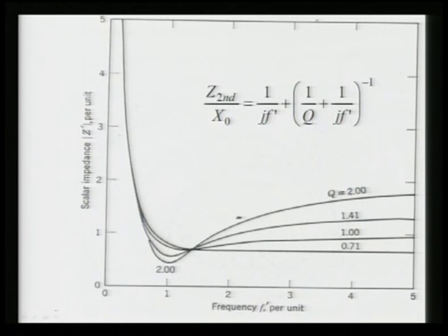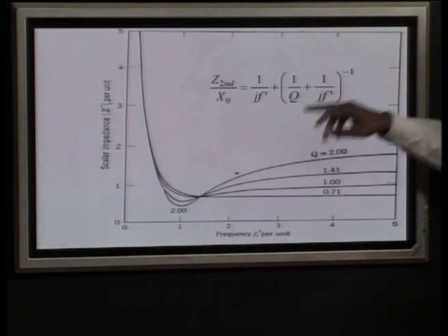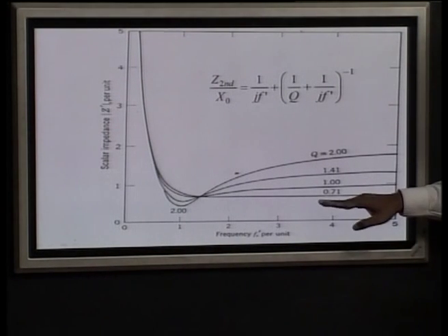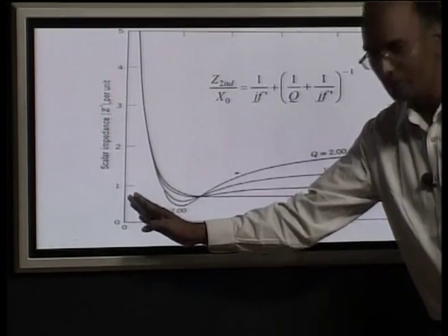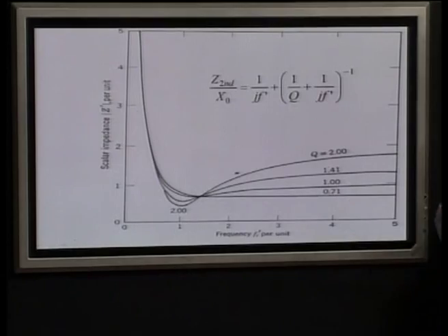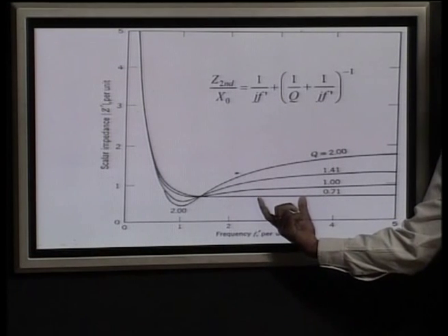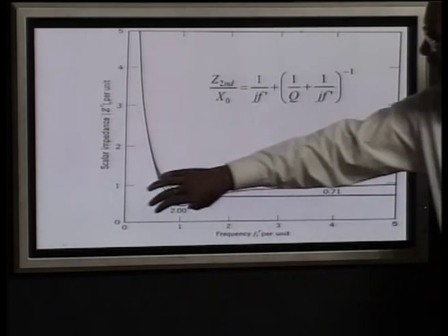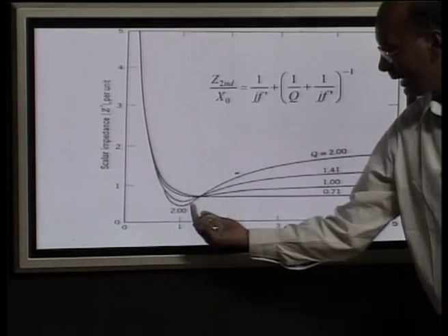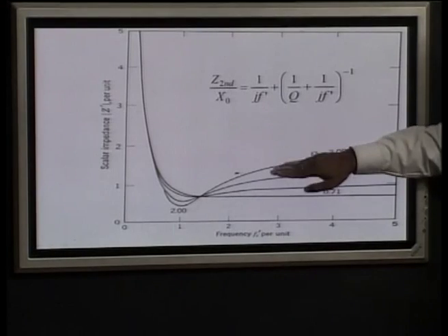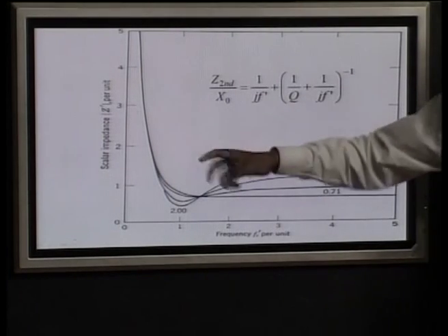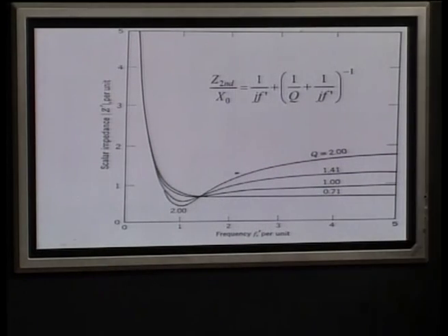For the varying value of your quality factor, if your quality factor is increasing, just see, it is going to be a tuned filter. As Q keeps increasing, you can see the Q is very low here, and now it is just coming here, it is just flat. We require this component where this should be passed and this is blocked. Again, how you are designing means it is providing the minimum impedance for higher order, high impedance for the low order, meaning it will only allow the higher order onwards to pass. So, once you are increasing this quality factor, this component keeps on rising, and normally it becomes a tuned filter.